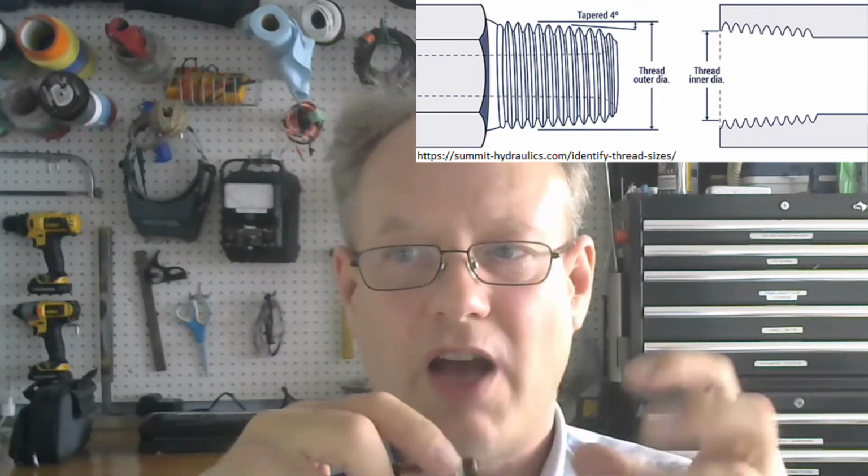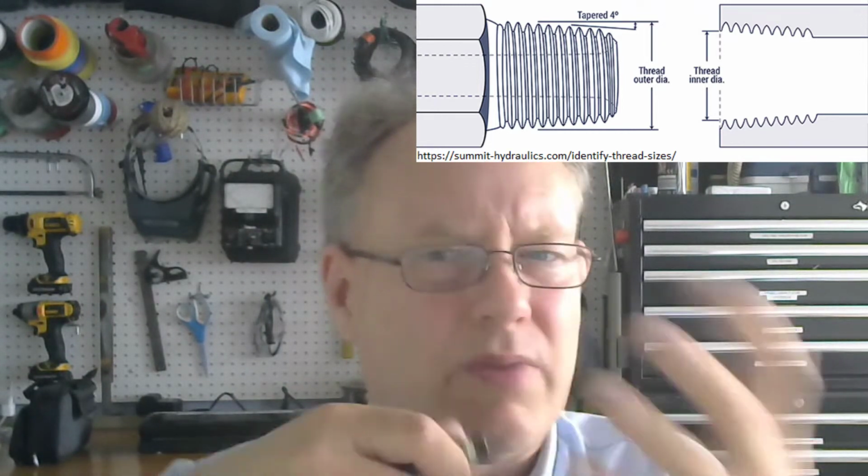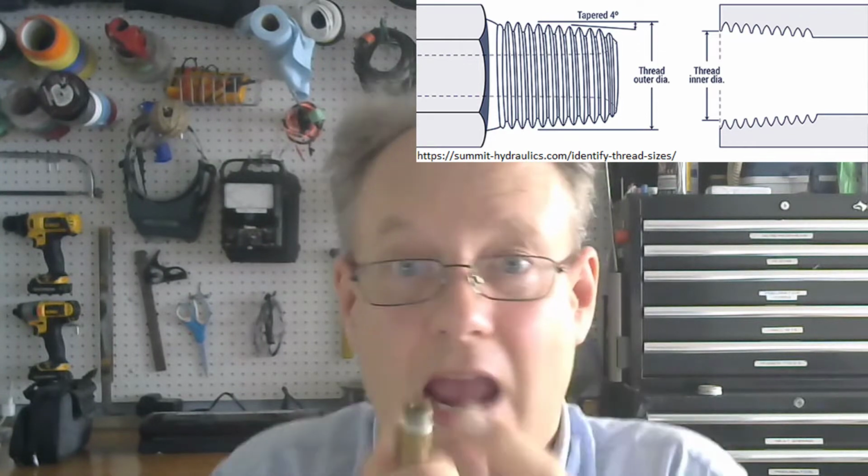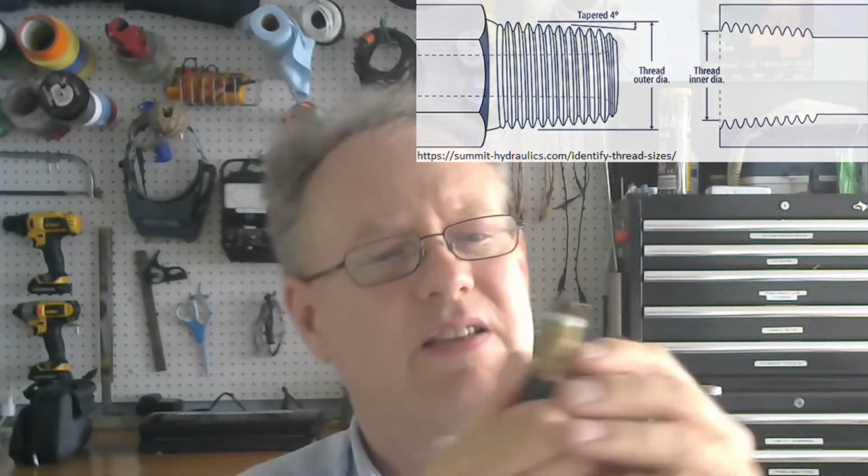And an NPT is designed specifically not to hold tension or deal with torque or compression. That's not its function, like most threads are. The function of an NPT is to seal a pneumatic connection. It actually creates a seal where air can't sneak by. For one thing, you can see there's a little bit of white on there, and that white is the Teflon tape that's on there. But this thing's tapered, and as I put it in, it slightly deforms, and the female part of that also deforms slightly.